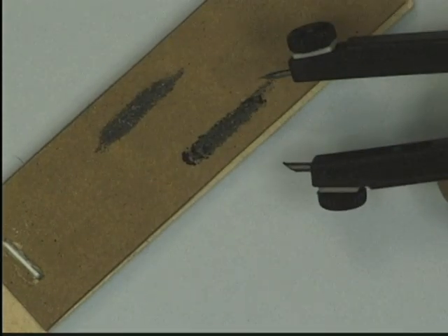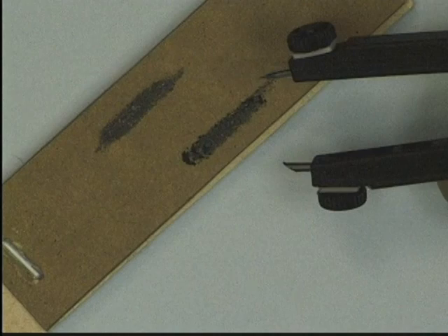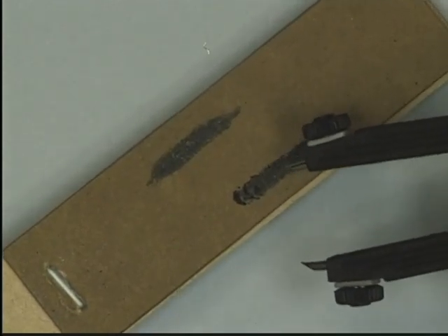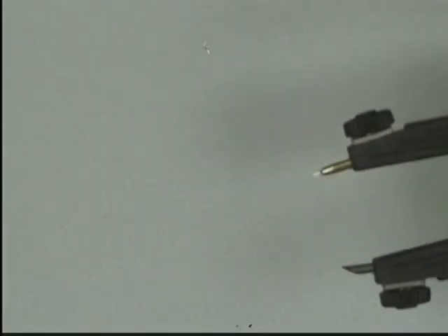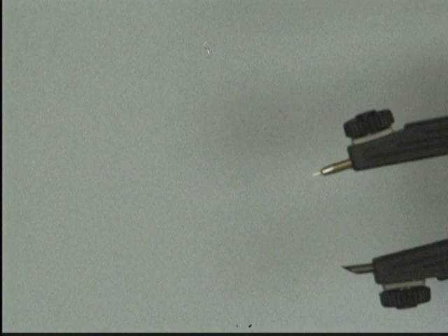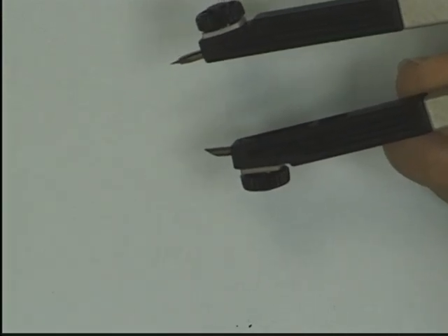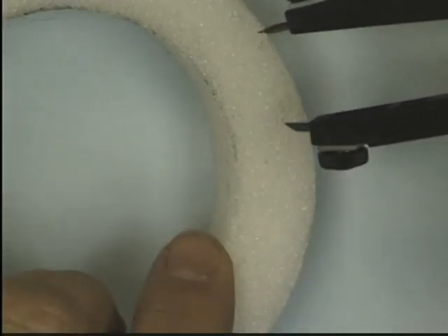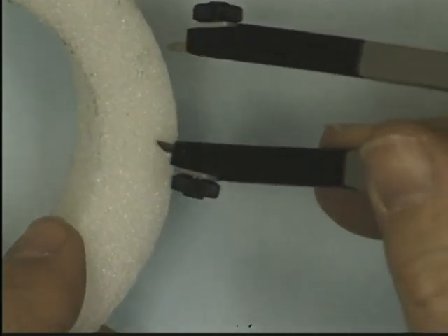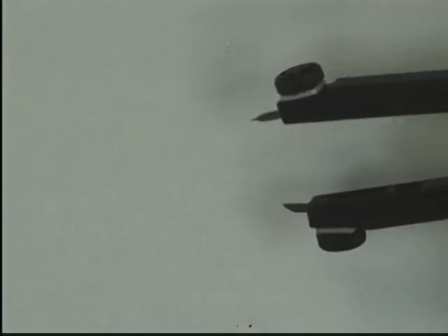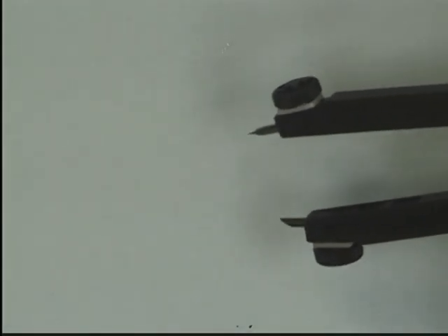Now I've got all that stuff. I shouldn't do this over the drawing table. I should do this over the wastebasket. I have one off to the side. I wanted to show you this, so I did it right under the camera, but I have a wastebasket right over here. And I can shake all that lead off. I also have a few lead particles clinging to that point now that I've sharpened it. So I can use the same ring or any piece of old styrofoam or an art gum eraser, poke that in and out and pick up those particles of lead, because I don't want them to fall on my drawing surface and get rubbed around and cause a gray ghosty smudge.